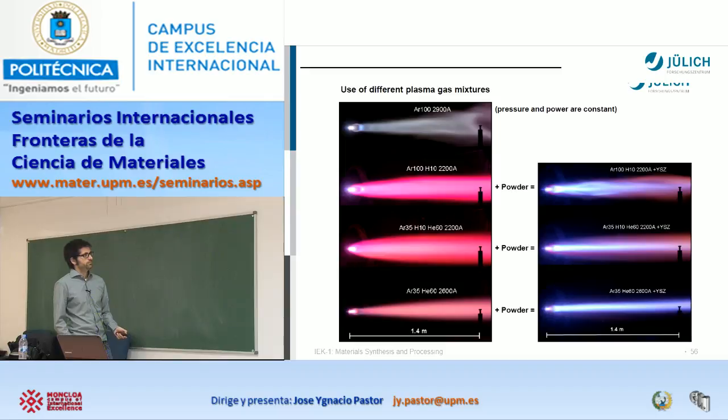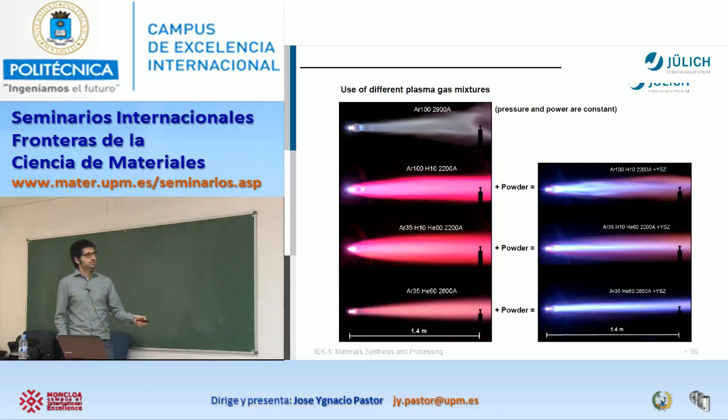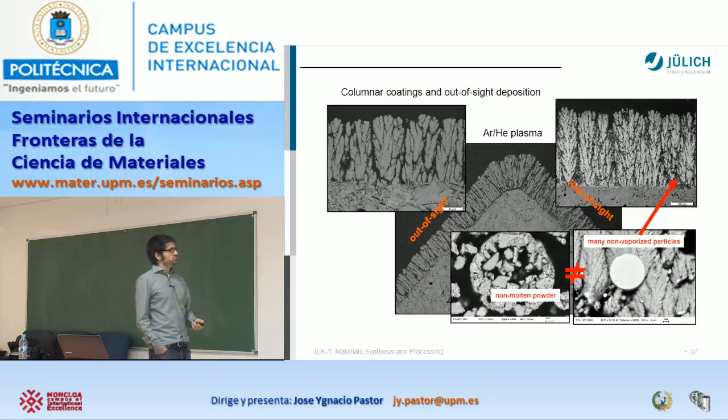And different characteristics, also depending on how it sprays, the velocity or the amperes that you use. And here, after that, when you introduce your powder, it starts to melt here, and impacts finally on your specimen. As you see also, if your specimen is here, you lose a lot of powder, because not all the powder that you introduce finally achieves your target. But also you can control, depending on different processes, that one or instead that one that is more wide. And this is the final microstructure that you obtain.